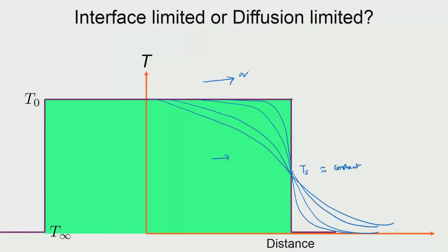Okay. So, the heat transfer is now diffusion limited, because as soon as the heat arrives at the interface it is able to go away into the ambient air by the heat transfer coefficient. Here you have got Ts minus T infinity. This is readily available. However, the temperature profile inside is not fully evolved, and very interior at the center of the body you see that the temperature is still T naught, it has not come down at all. So, this is a situation where, for example, you have a non-conducting body like a ceramic, and which is exposed to air, and then the temperature is supposed to drop.